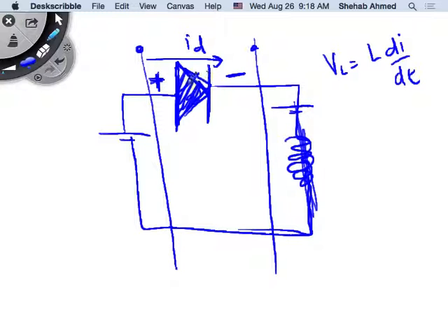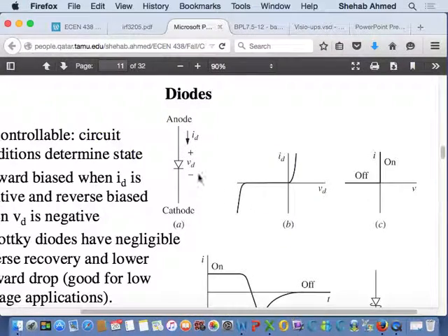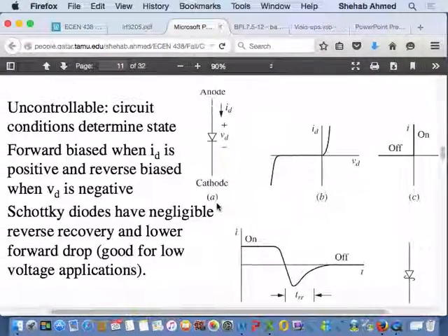So if it's not conducting, it's an open circuit. If it's an open circuit, what's the voltage across the diode? And then this is VDC2, for example. Yeah, it's an open circuit. What's the voltage across the diode? VDC minus the difference in voltage between the two sides, right? Or if I didn't have this one here, then it would be VDC, right? So it will block the voltage across it if it's not conducting.